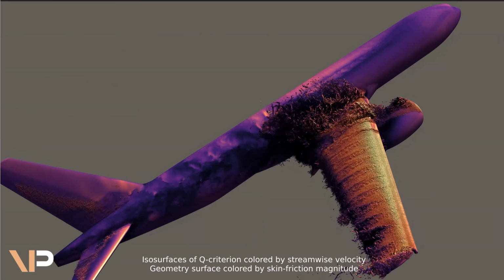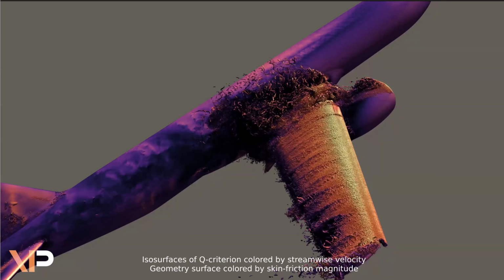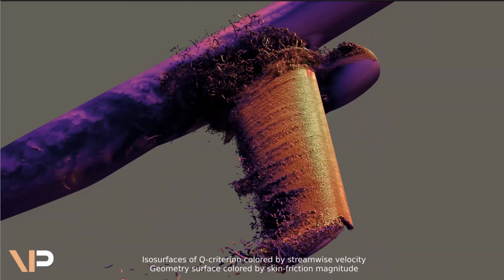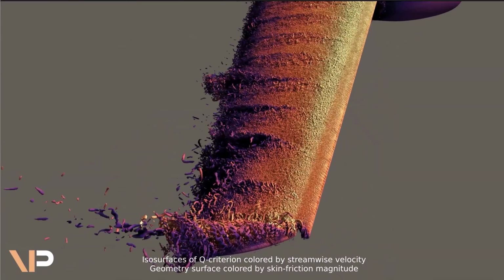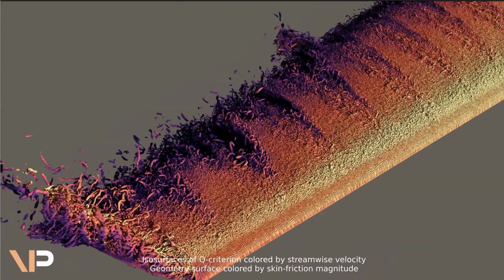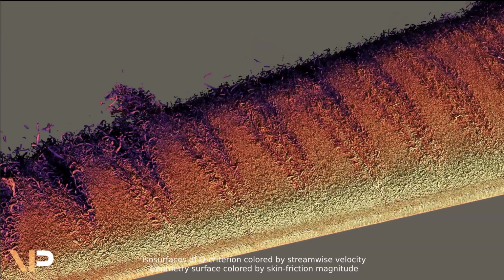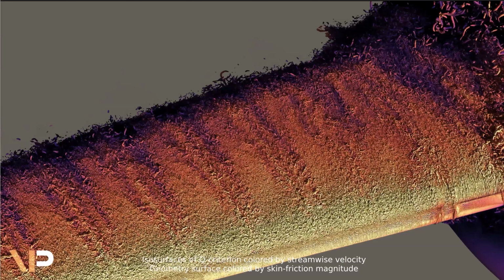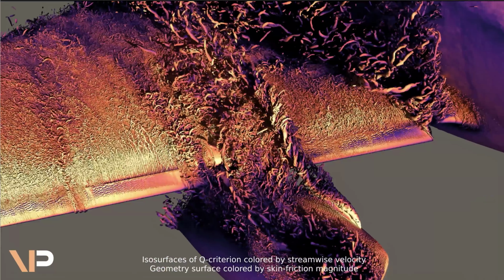So we don't want to be lucky that error cancellation gives you good lift and moment. We really rely on one model, LES, which is really not relying on any coefficients or anything. As long as you have space-time resolution, you'll get some grid convergence, and maybe modeling errors can still be due to the wall modeling, but you don't rely on anything else.